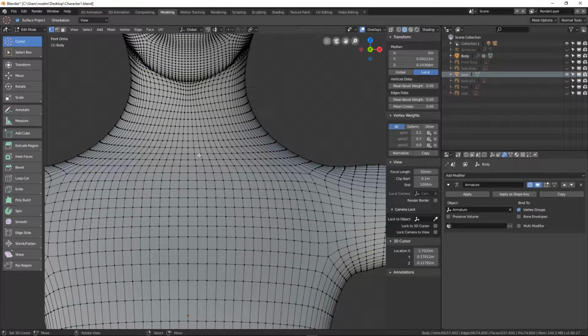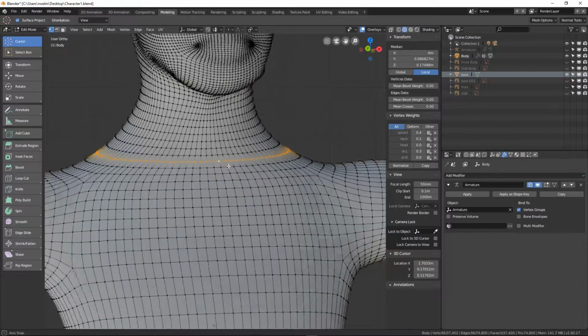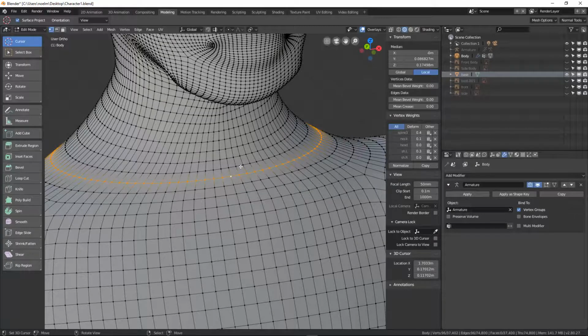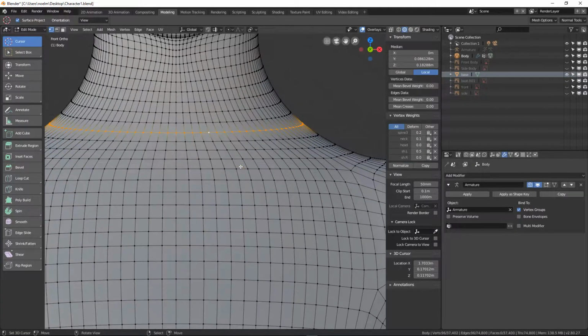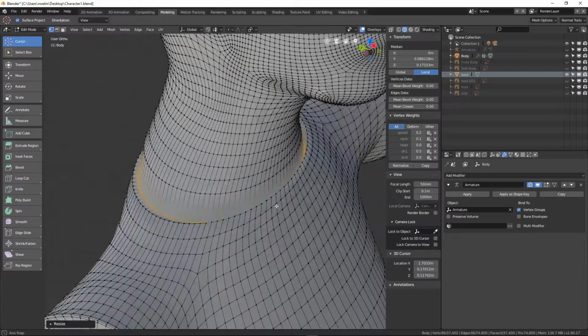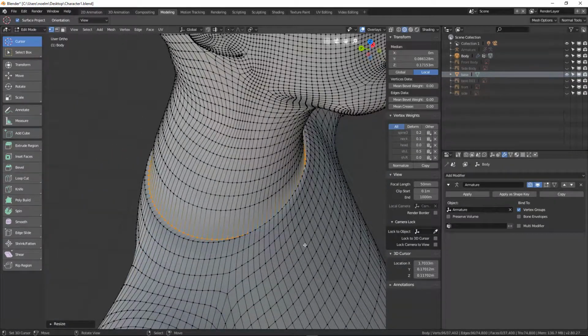Like I said, we could add in these seams using sculpting, or simply using polygon editing. So I'm going to go G, Z, and move this down, and then press S and scale out a bit, and scale that on Y fractionally.